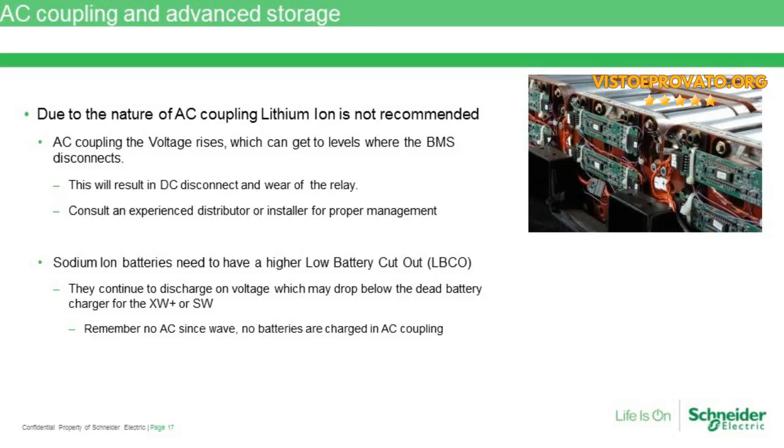As long as we're over that kind of 440 amp hours for the XW Plus or 200 amp hours for the Conext SW, then that suddenly starts to make more financial sense to the customer and could get you to convince them to start with a battery-based system with just the overall cost and getting the most of the return on investment out of that system. There are exceptions, of course, when sizing out for lead acids versus some of the more progressive technologies, including lithium and things like that. They're sizing out for nearly 100% depth of discharge from the start. So you can definitely take that into account.